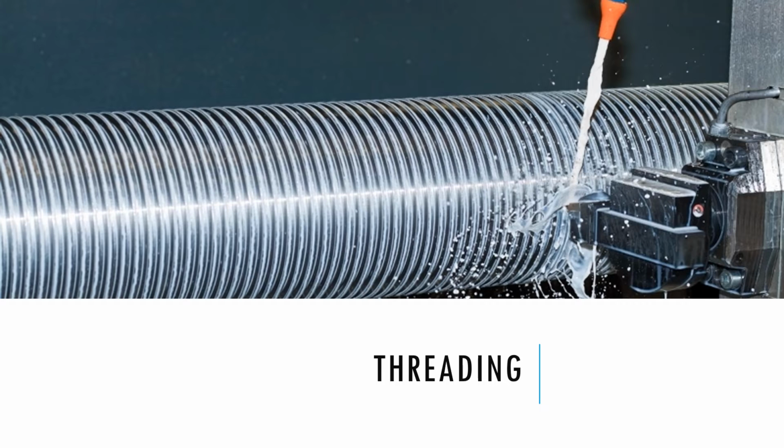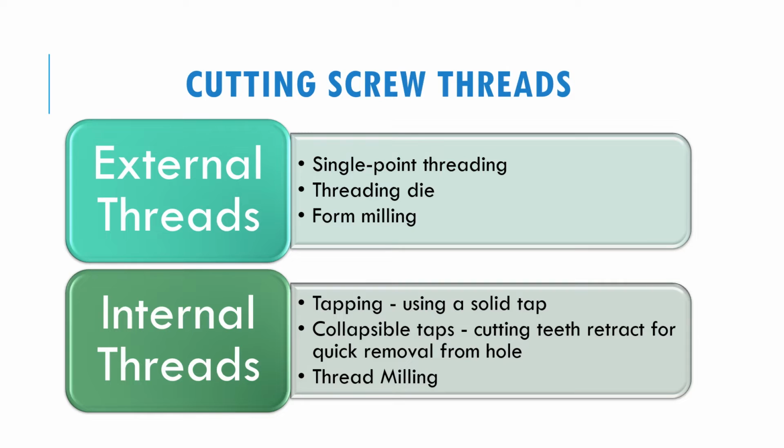Now let us look into the threading process first. We have two types of threading: external threading and internal threading. There are some processes that can be used for each. For external threading, we can use single point threading, threading die, and milling. As for internal threading, usually tapping, collapsible taps, and also thread milling can be used for the machining process.